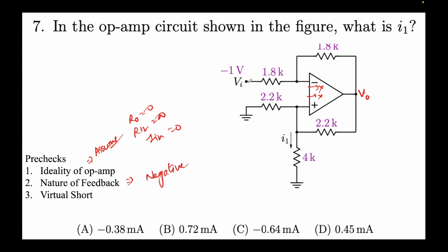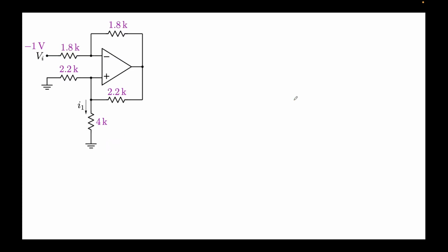And plus, the input is also applied over here, right? Whatever output is being fed, here it's fed through different resistors, so that also plays a role, and we'll see how it says virtual short. Again, we'll assume it is operating in the linear region, and hence the negative and positive terminals are sitting at almost the same potential. All right, so let's do that.